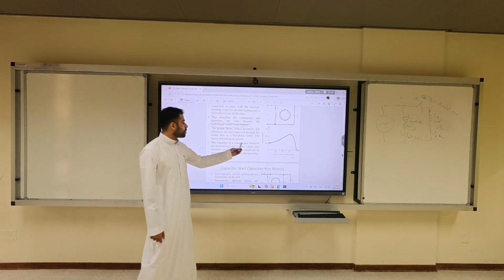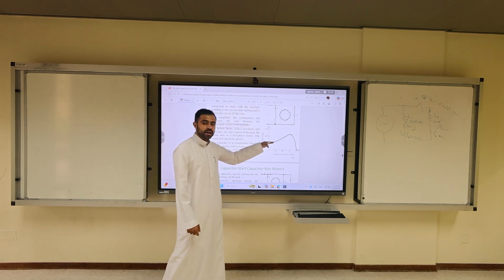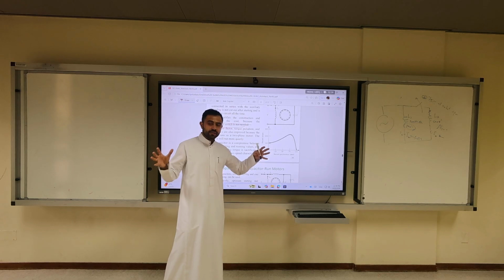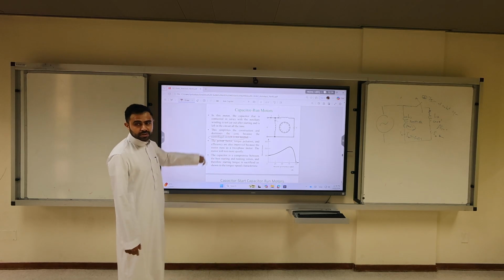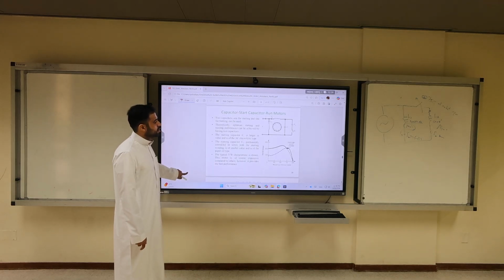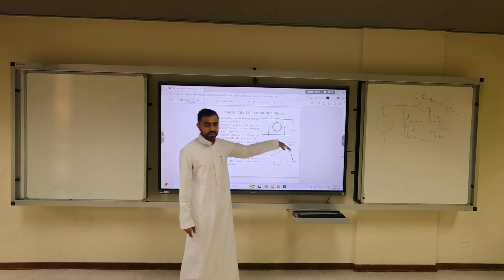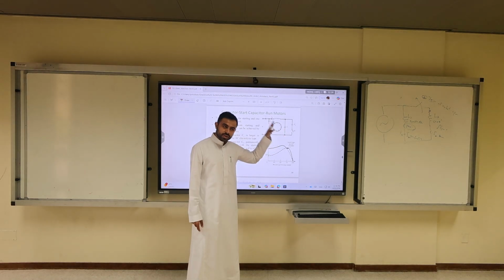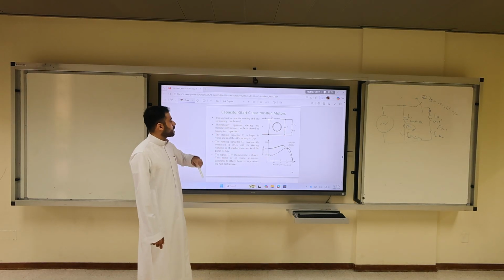The capacitor is a compromise between the best starting and running value, and therefore starting torque is sacrificed. You might not achieve very high starting torque because you have to make your capacitor smaller. If you make it big for operation, it's not good. So I wouldn't use it much. But there is capacitor run mode. There is also capacitor 1 start, capacitor 2 start. Two different capacitors, one for start, one for run. Which is another solution. Again, two capacitors, one for starting, one for running.